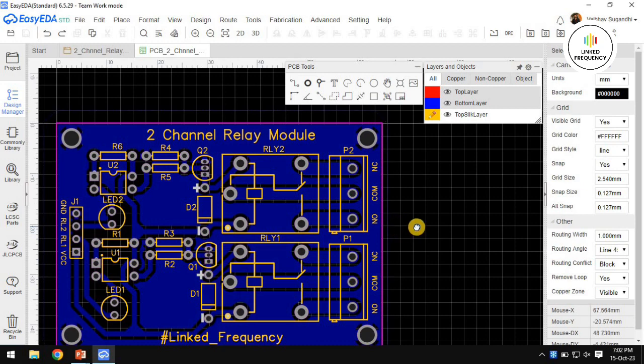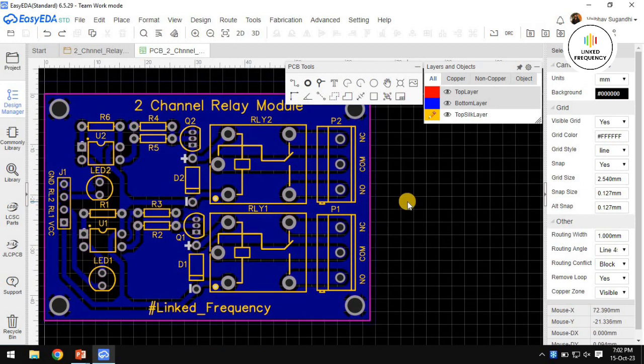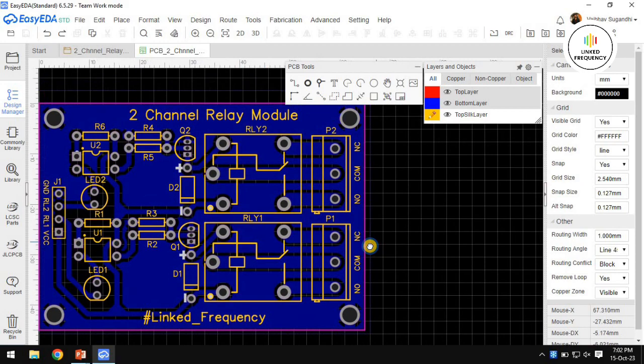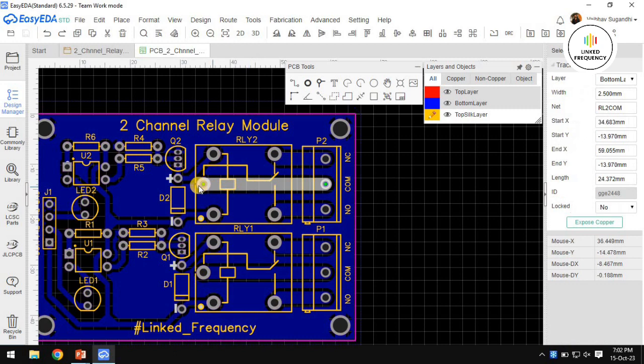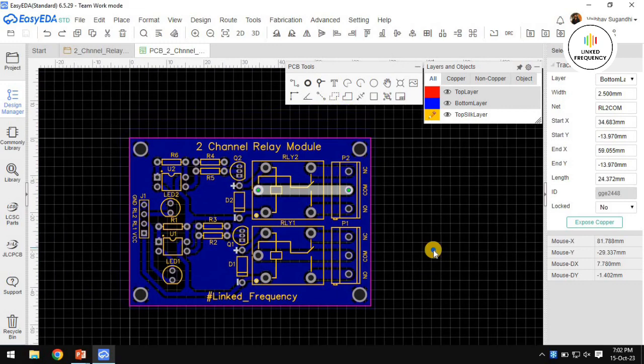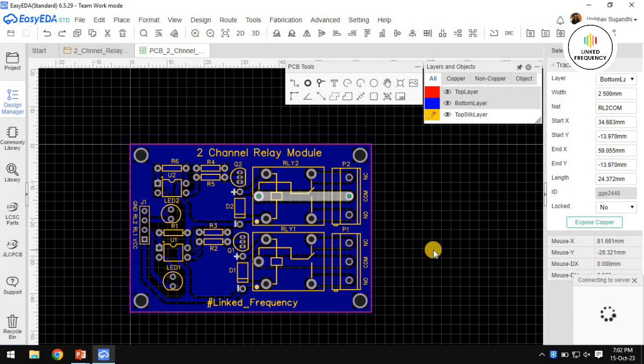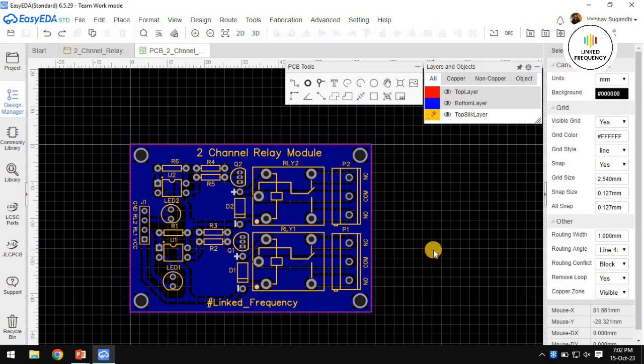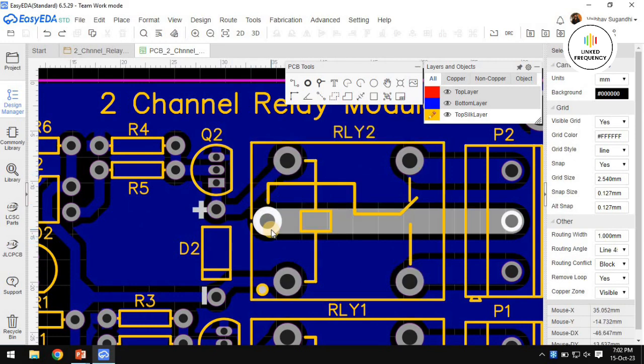Again, since it is a beginner tutorial, I don't want to put up a lot of components or a lot of learning points in a single video. That's why. So make sure that you at least follow the same circuit design or the PCB track method that I have shown in this particular video. Other than that, you can explore different component placement, play around with the transistor as we discussed, and also try with the creepage clearance.